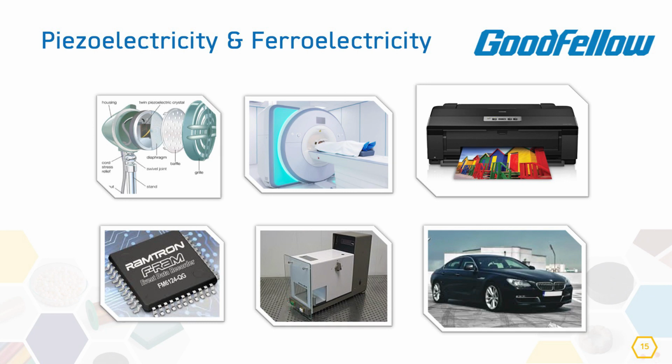Again, a piezoelectric crystal in an inkjet printer. A set amount of ink needs to be let out of the nozzle at a set amount of time. Now, if a piezoelectric crystal is there at the nozzle, say it is closed, we apply a voltage and we can expand that crystal and open it slightly, let out a bit of ink, take away that voltage, it closes back over, it can find an application in an inkjet printer.